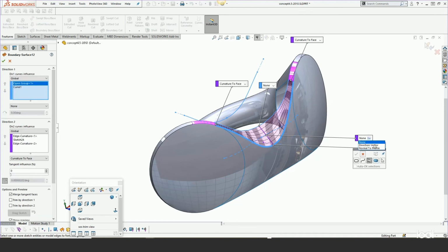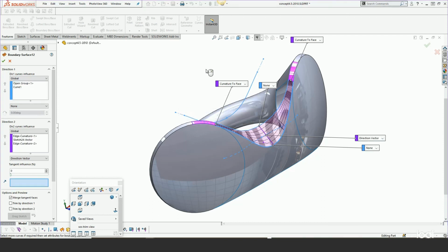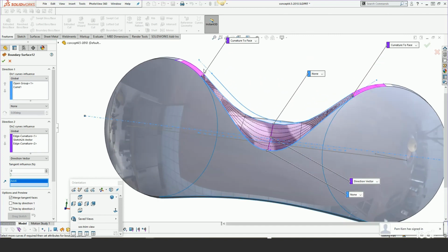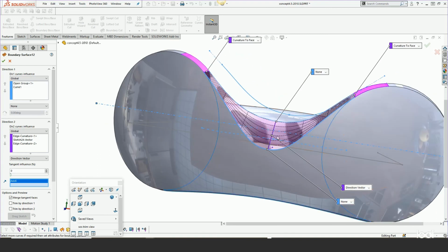And here, let's turn off our selection manager. Do this by a directional vector. And if I show that, now I can fill that in. So here's the dialog box for that. And I filled that in. Now it's not going to make much difference because these are identical curves, and I've been careful to make these second direction curves pretty symmetrical around the right plane. But it does give a little bit more assurance that everything is symmetrical across this interim curve.